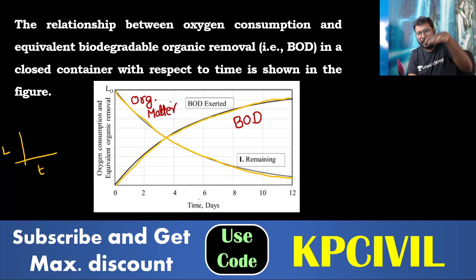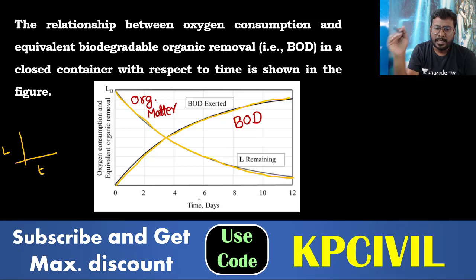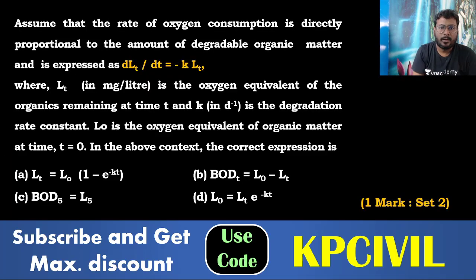Because organic matter falls exponentially, BOD oxygen consumption increases exponentially. Now, assume that the rate of oxygen consumption is directly proportional to the amount of degradable organic matter. dLt/dt is equal to minus kLt. Simple equation only. We know it, first order rate kinetics. It follows first order rate kinetics. We have derived it also.